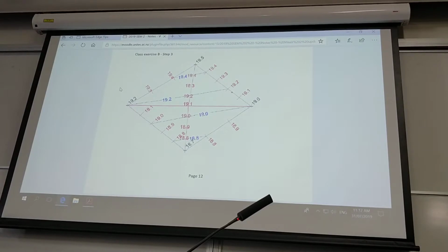I had a degree student who calculated it all completely wrong, which was embarrassing, but okay, so we've got a height difference of 0.56 between these 2 levels, and we've got an overall distance of that. What we're trying to find is this distance x here. So we have another triangle here on the same slope. We've got to find x, but we do know the height difference between 44 and 81, even I can do that, 0.19.